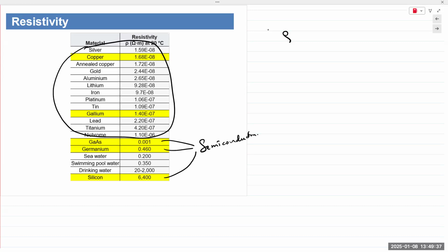So you have an atomic structure. You have electrons orbiting around the nucleus, and each of those are fixed, at least that's what the latest model is, right? They are fixed and they have a fixed energy level. But the energy in these electrons does not exist in infinite levels. They are discrete levels. They are quantized. And so each electron is occupying an energy level that comprises a certain band. So you get different energy levels and different bands of energy. And if you plot a two-dimensional diagram of those energy levels, we get what is known as the energy band diagram.